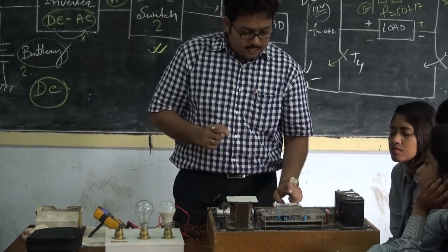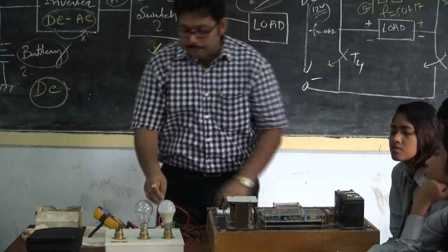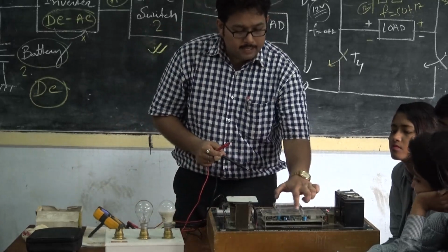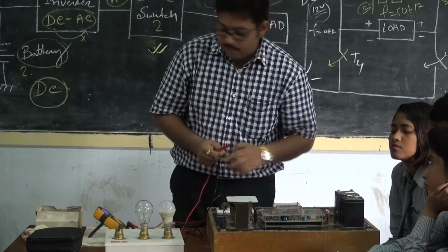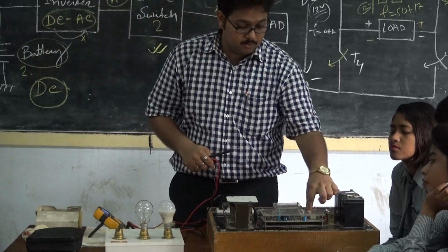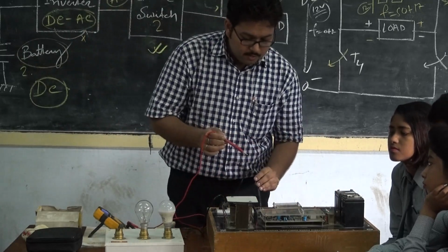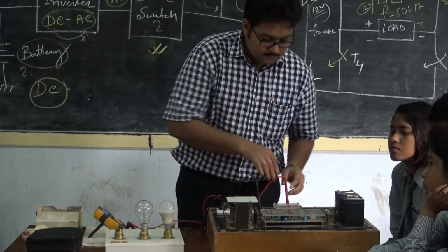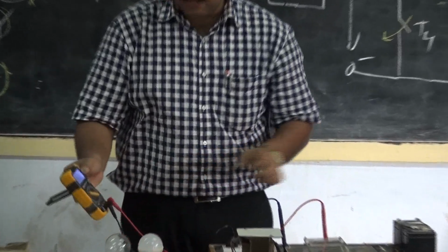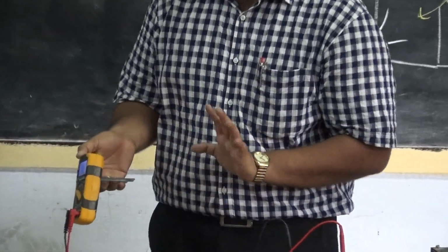Okay. Then fault switch F3. What is the purpose of fault switch F3? Fault switch F3 will supply the 5 volt supply to the main circuit. Okay. Now the main circuit voltage can also be seen by measuring the voltage at this test point. What is the voltage at test point 3? It is near about 5 volt.